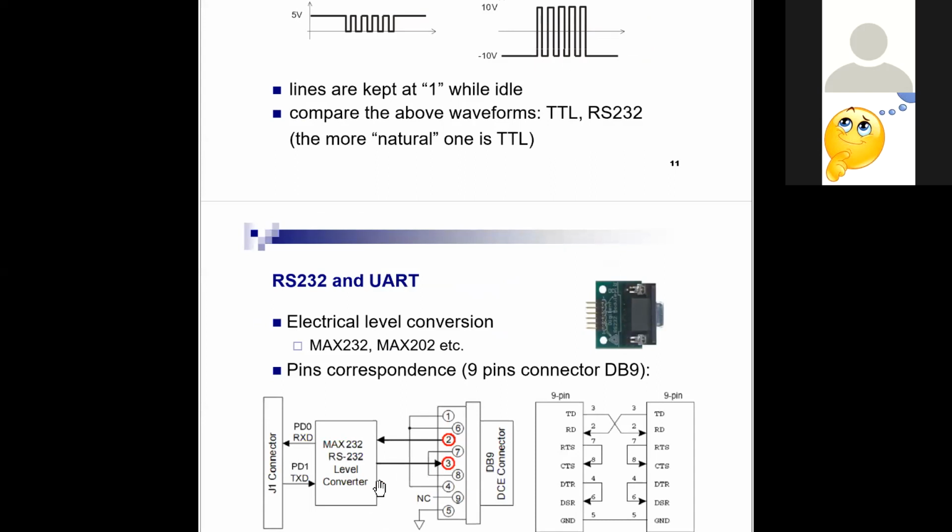Okay. So you have seen how they were connecting this RS232 cable. You all know we will receive the data only in parallel. So while receiving the data in parallel, we will convert it into serial, and then do the communication. At the end of the communication, again we will convert the serial data to parallel data. So why is UART not popular? Because of the level of voltage they have fixed, and another one is that there is no handshake signal.